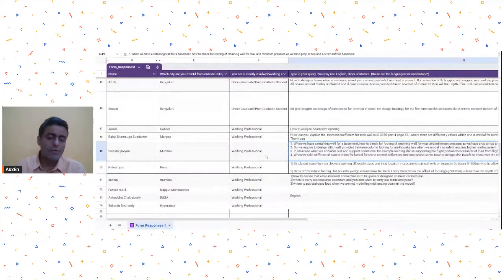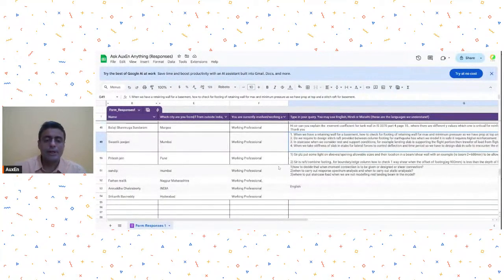Okay, why don't we usually do it in Indian practice? Because in Indian practice, we usually have thick RCC slabs, not like Western America. I mean, by Western America, I mean America and Canada and those Western European countries where they do a lot of timber construction, where their diaphragms or slabs are not very stiff in plane. Contrary to that, we have quite stiff slabs. So we are usually not very worried about this diaphragm issue.